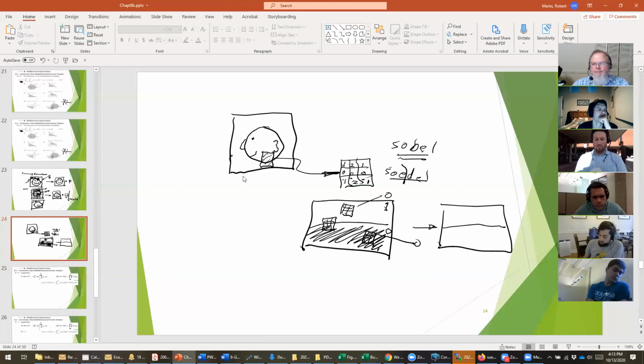Dr. Mars. Yes. So this grid that you have here, does each box represent just one individual value of T1 and T2? Yes, this is not T1, this is discrete. So these are pixel values. This is N1 and N2. So it's digital. So we don't shift continuously. We shift by the next pixel, the next pixel, the next pixel. So we're not doing a continuous sweep, but this is the digital equivalent of two-dimensional convolution. Exactly the same sort of mathematics.